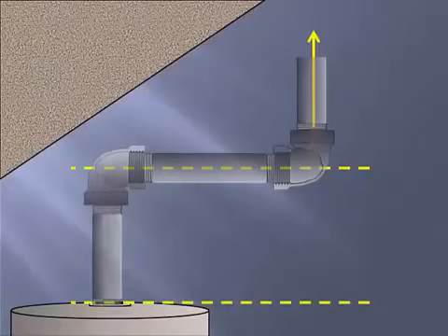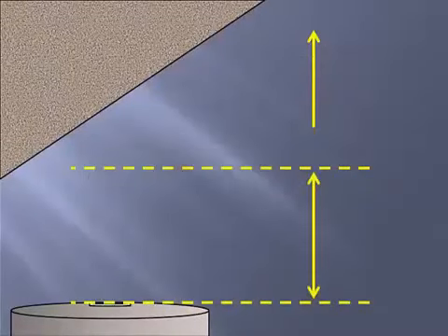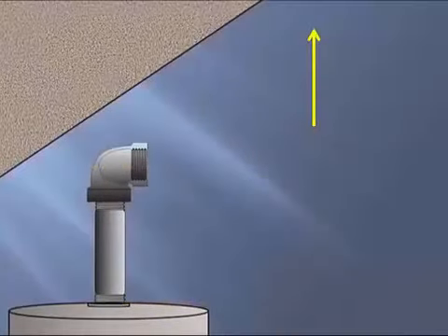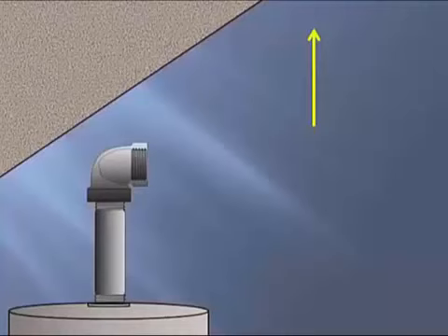So we take a measurement and cut a piece that allows us to install a 90-degree fitting, which brings us up to about this location. What we'd like to work on for today's lesson is how to take a center-to-center measurement, subtract for the fitting allowance, to accurately cut the end-to-end piece required for the offset.